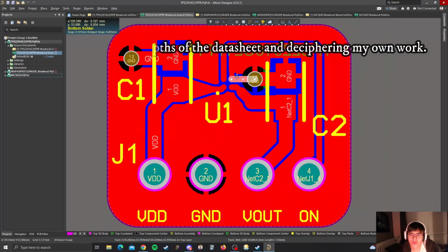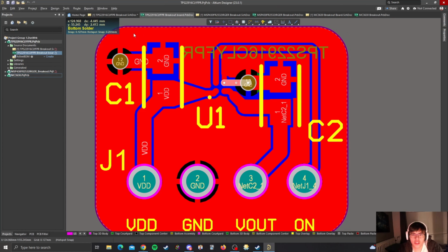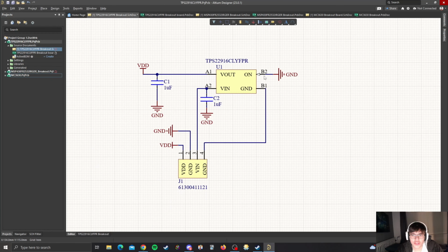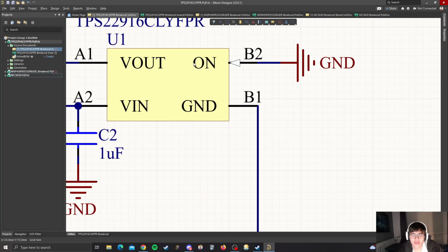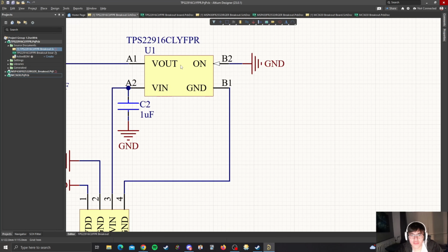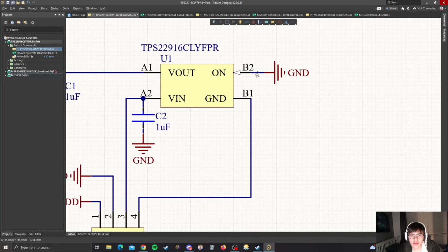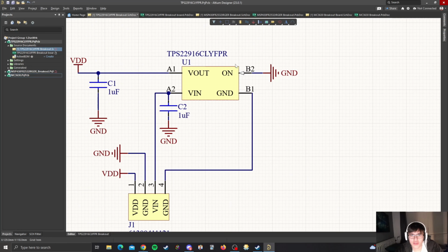So I've had a read through it, and this is just a standard load switch. High would be on, low is turned off, and over here it looks like I've labeled this down to ground, which should be, well, this device is always off.